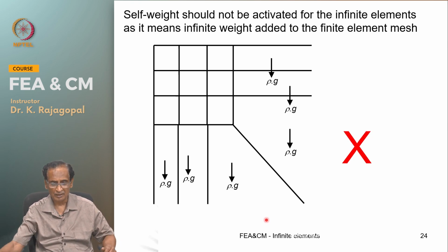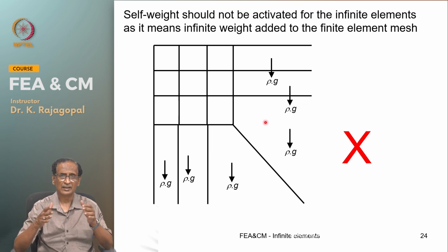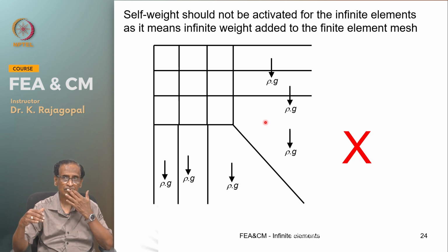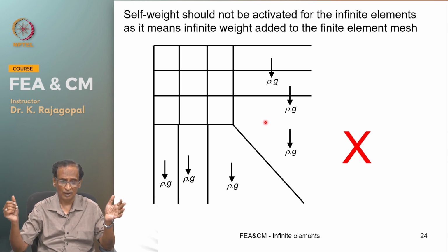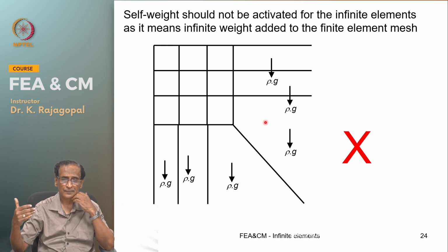And the other precaution is, we should not activate any self weight on the infinite elements. This is also very important, because these infinite elements represent infinite volume, and loading on the infinite elements means you will have tremendous loads in the load vector.